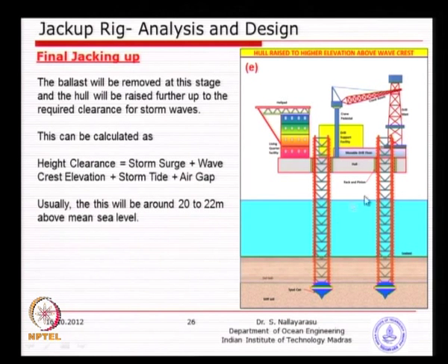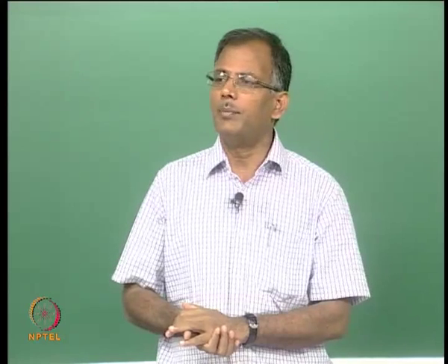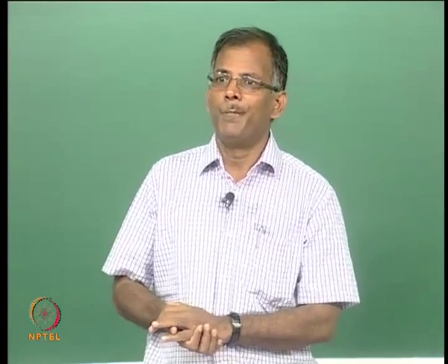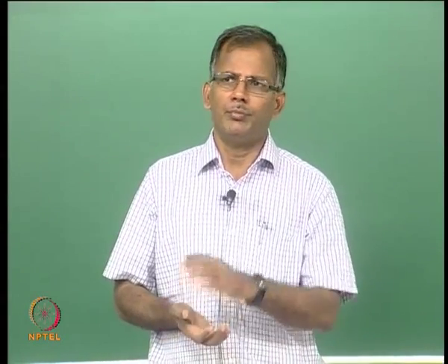And the basic idea is you move this up, making sure that there is no green wave effect on the hull itself, because that will be a substantially large force which you will not be able to stabilize in these jack-up rigs. I think that is what happened when many of the jack-up rigs got drifted during a cyclonic storm in the Gulf of Mexico. I think you might have read the internet news back in 2005.